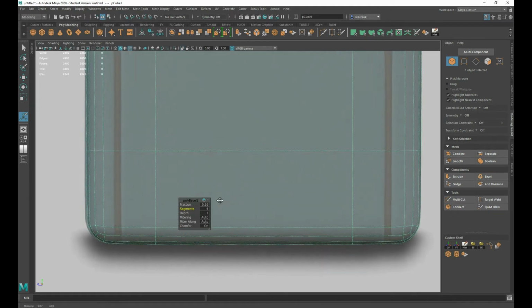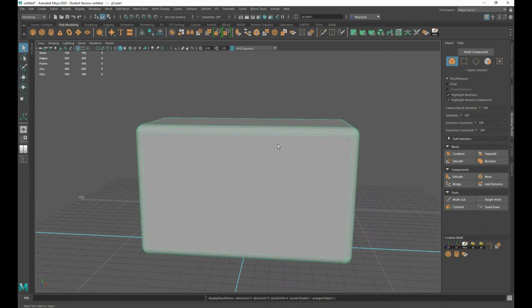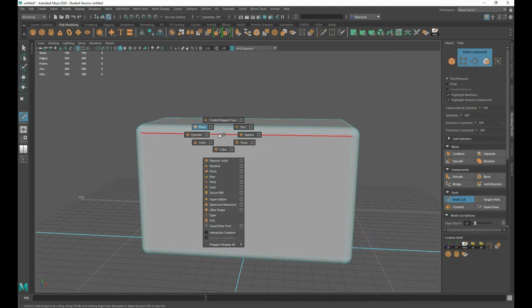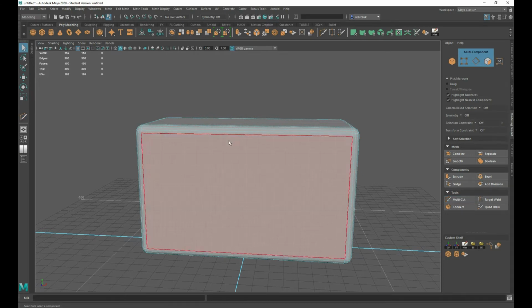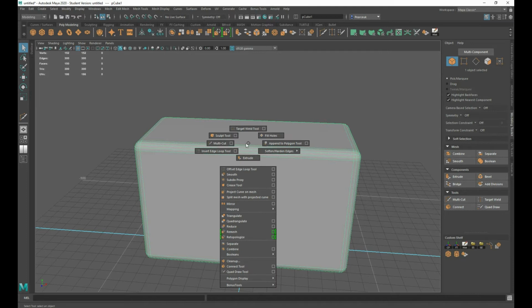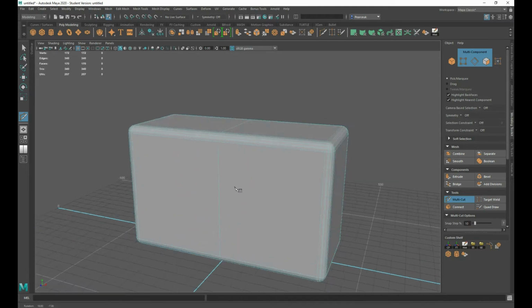And you see as we go through. And we can also model, and what I also like to do when I'm modeling is I'll have a multi-cut, so shift right click, once in option mode, so Q to quit out of that, right click in option mode, shift right click, and I'll go to multi-cut, and then I will hold down control, and if I middle mouse click, it will automatically position that in the middle.